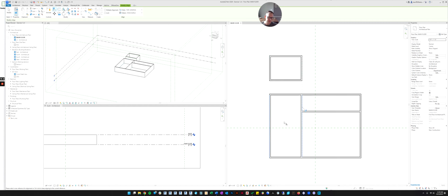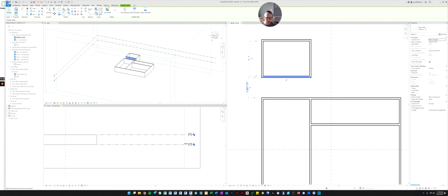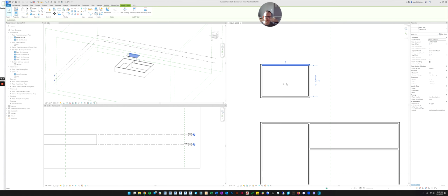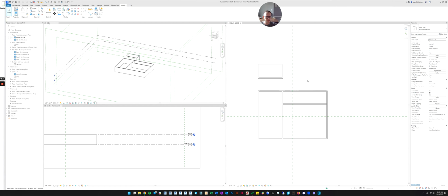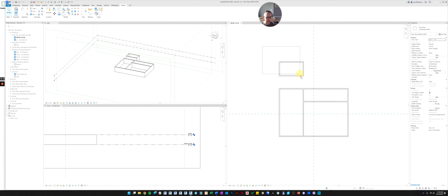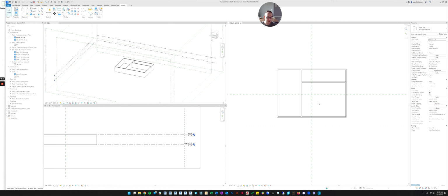And now it's aligned. Now if we want the shed to be 10 feet away from the house, we can click on this wall, because this is the wall we intend on moving, and type in 10 and it'll move it. Now let's make the shed, let's say on the outside. The outside of the shed should be 12 feet deep. And there we go, there's our little shed. Okay, then we're just going to delete that because that no longer matters.